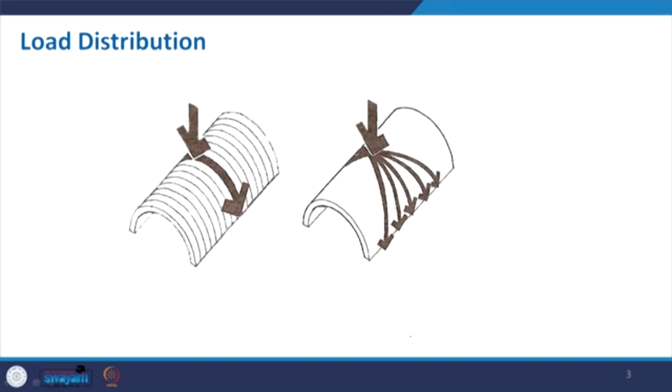So, what you can see is that if we just consider this single part, suppose we take only this much, this is basically an arch form, maybe made of masonry, maybe of concrete. Now, when you look at it individually, we just place it one after another separately. So, each one of them is carrying the load individually. Applied load is applied here and it is being transferred like this to the surface, and mostly it is in compression. And when we make the vault continuous, you can see the resemblance between these two shapes.